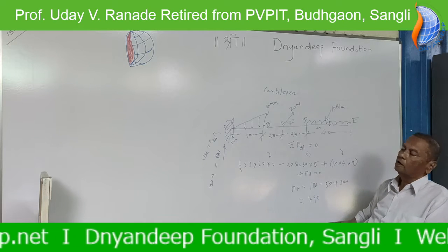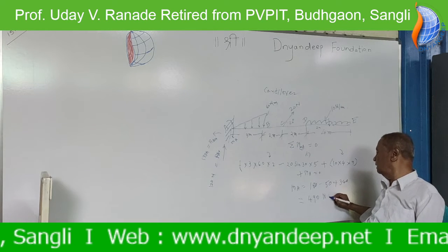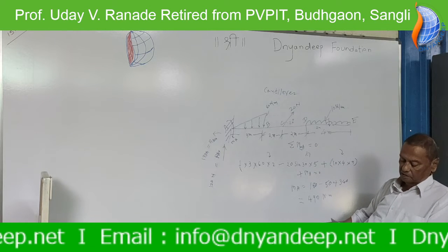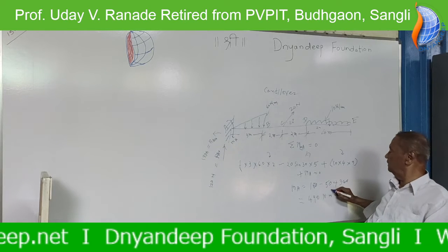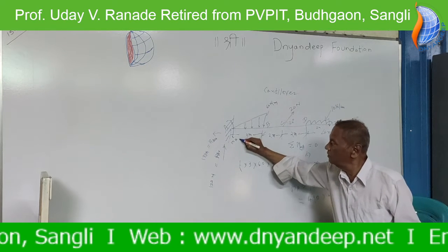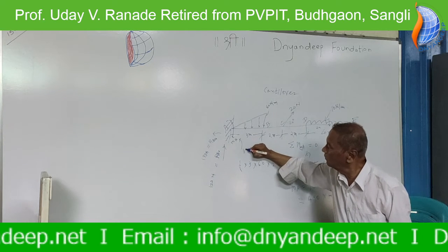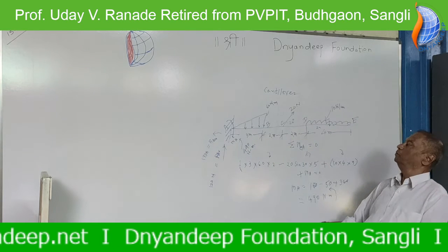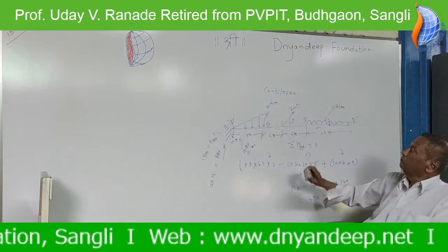And what is 490? Unit of 490? It is Newton meter because it is moment. And if we see the direction, that direction comes after calculating and after giving sign, anti-clockwise. So MA is like this, anti-clockwise, and its value is 490 Newton meter. This is the problem of cantilever. One more problem.